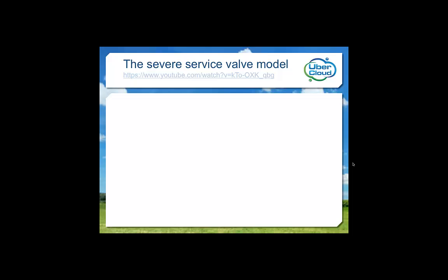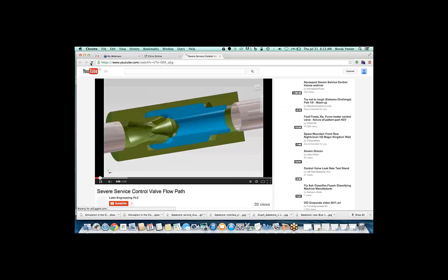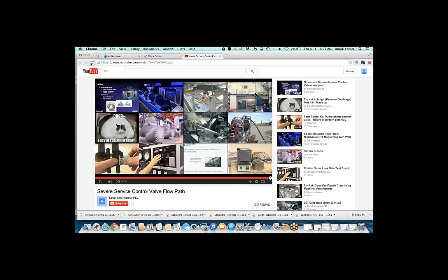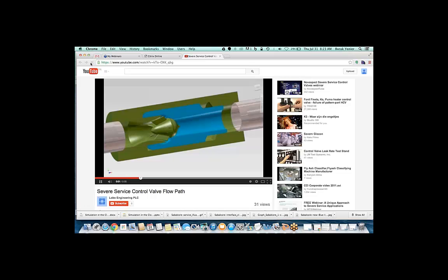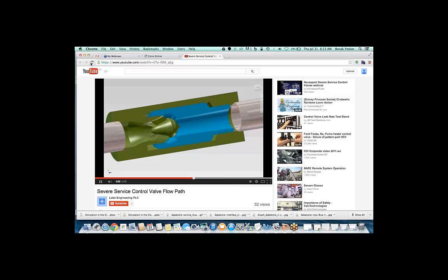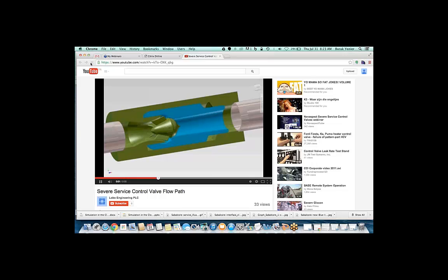For the purpose of this experiment, I wanted an ideal flow path. The valve should have a straight body with simple inlet and outlet transitions. The restriction, or trim in control valve parlance, should cause gradual velocity changes and minimize direction changes. The low static pressure of the fluid at the exit of the trim that could cause a fluid to vaporize should be kept from recovering when fluid impinges on the flow path boundary. Remember, I was looking for a very high F sub L.